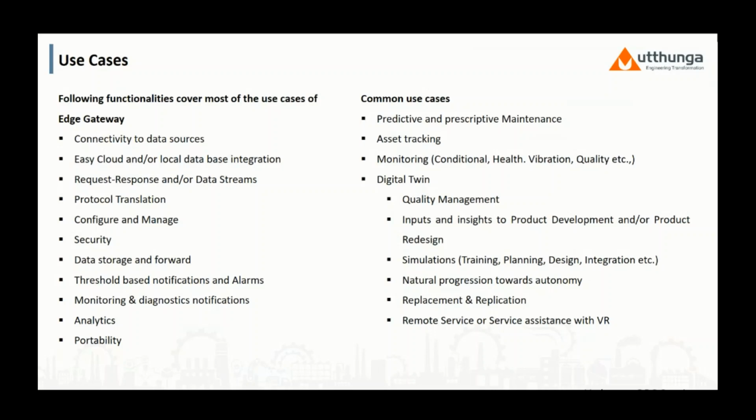Or in some cases, the edge can continuously send a stream of data. For both, OPC is suitable. The client-server architecture works in request-response mode, and the pub-sub specification uses JSON encoding and AMQP or MQTT messaging for publishing the data. So in both modes it works.